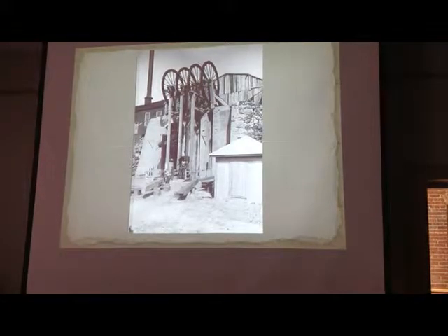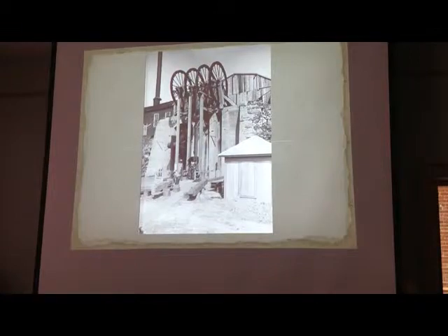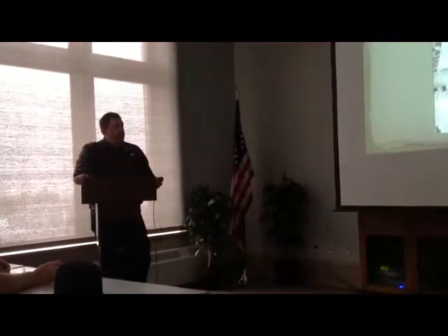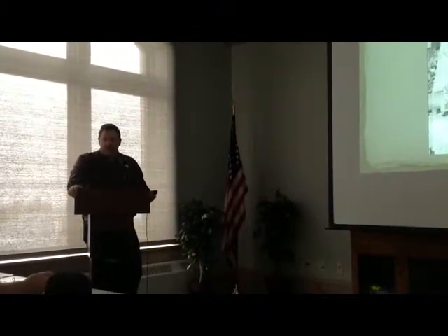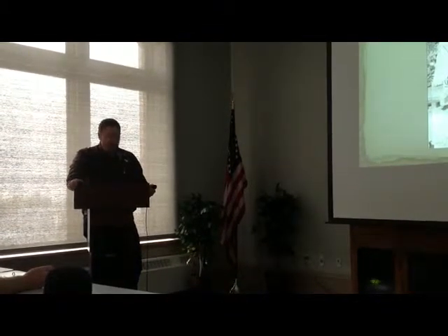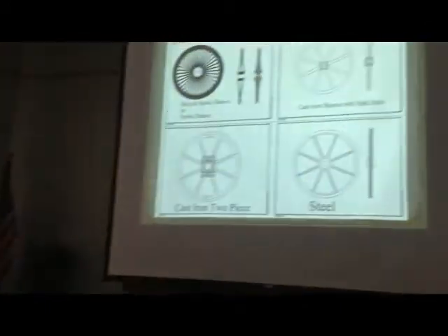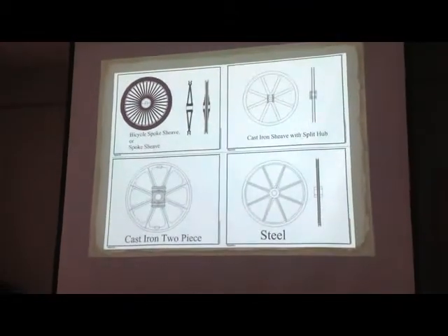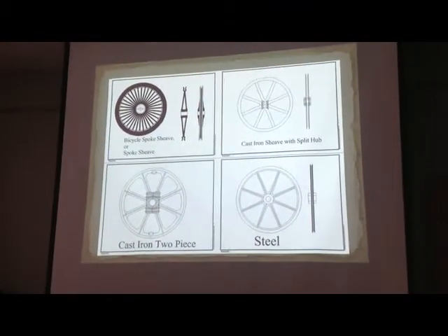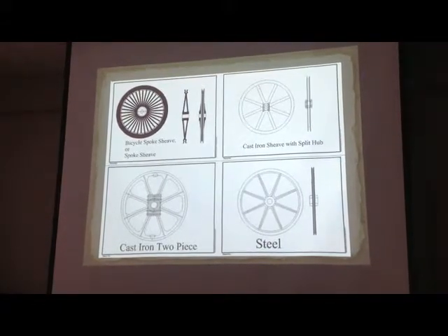As we get into Montana, things change a bit. You know, this is expensive. Most mine sites are never meant to last more than 10 to 15 years, so you can't afford to put up a monster masonry structure at this time period without spending more money than you've got coming in. So basically, from the top down, you have the steel arch or crown of the head frame, next the sheave wheels and sheave bearings, then your front legs and back legs, and your guides.